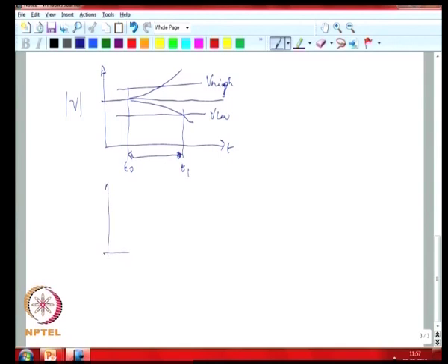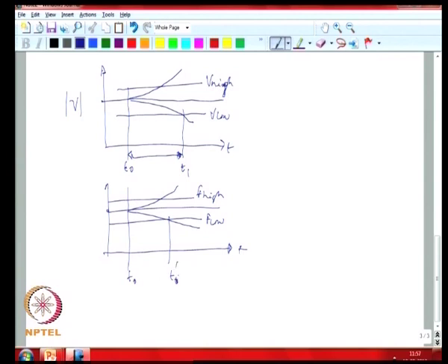you are looking at your frequency versus time. You have, say, a nominal frequency, and at T naught your upstream switch disconnected, and then you have an F high or an F low, and depending on when you are able to detect that the frequency went out of bound, you can trigger the relay at your DG source that your operating condition has gone beyond the acceptable range.